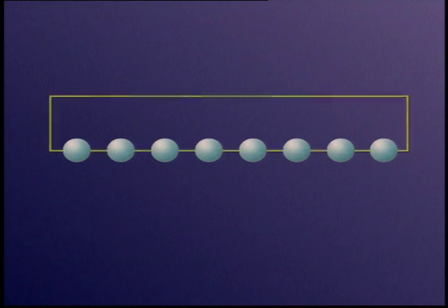Thanks, Steve. As previously mentioned, CRAY T3D processing elements, or PEs, communicate over a high-speed network configured in a three-dimensional torus topology. What's that? Well, to illustrate, let's start with networks having less than 3 dimensions. This is a diagram of a simple single-dimension torus network connecting 8 nodes. The links between them carry data packets at some maximum rate we're not concerned with for now.